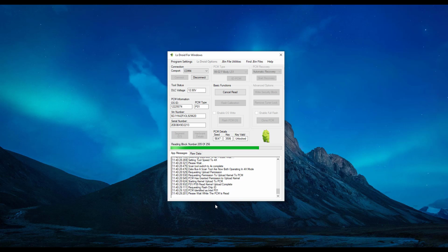On that note, with a bench wiring setup, make sure your wiring is 100% correct before you connect up an ECU or an actual scan tool. Otherwise you will run the risk of damaging either the engine computer or the scan tool. So that's very important. Make sure you've got that double checked. A recommended group to speak to is the LS Droid group or even the PCM Hammer group. Plenty of people are more than happy to double check that you've done it all correctly before you proceed.